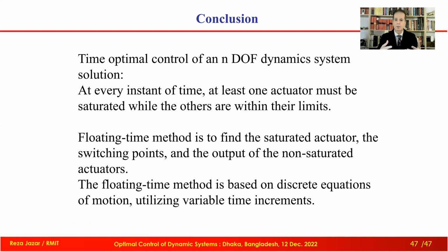We must add some other realistic parameters to the equations of motion, and there must be feedback, because at the moment this control is blind. We apply those torques and we expect that the end effector moves on the path that we designed from the beginning to the end point.